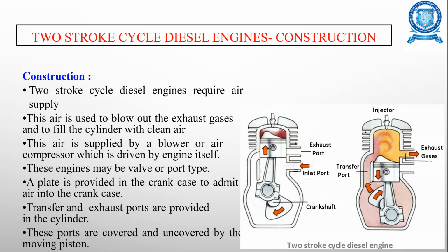The two-stroke cycle engines require air supply, and the air is used to blow out the exhaust gases from the cylinder, and fresh air will be filled in this cylinder. The required air is supplied through this inlet port by means of a blower or air compressor, which is driven by the engine itself.